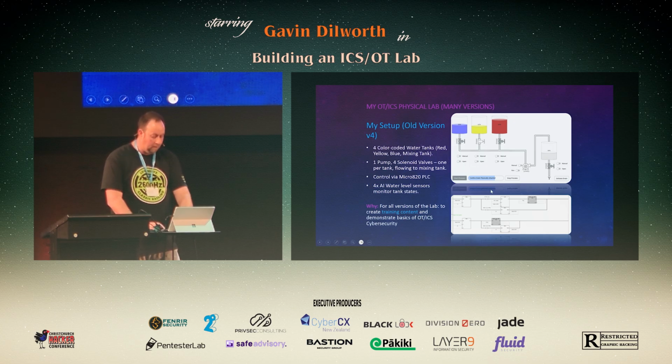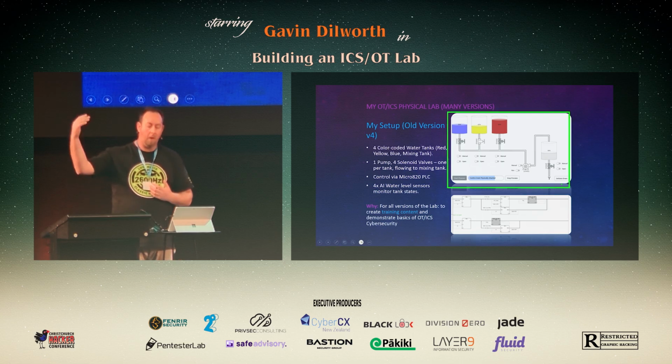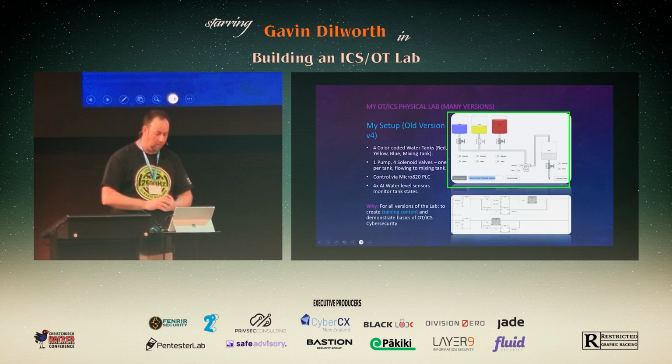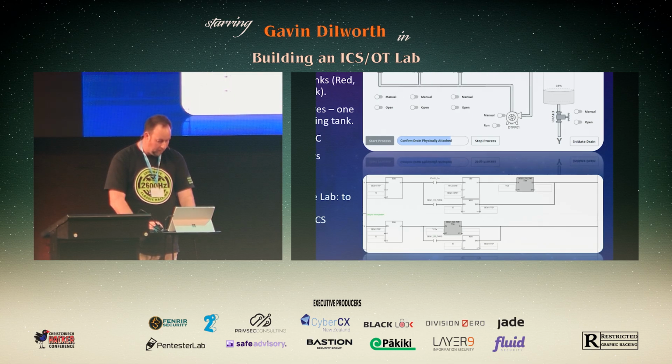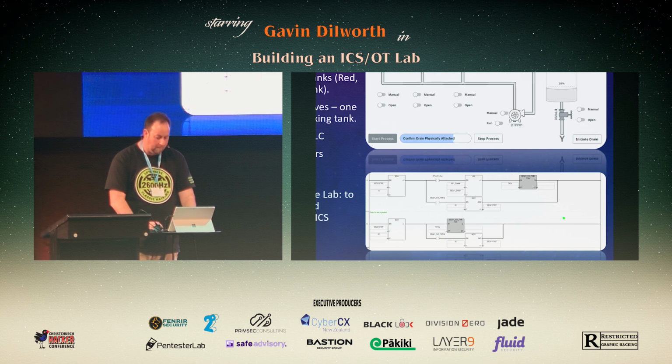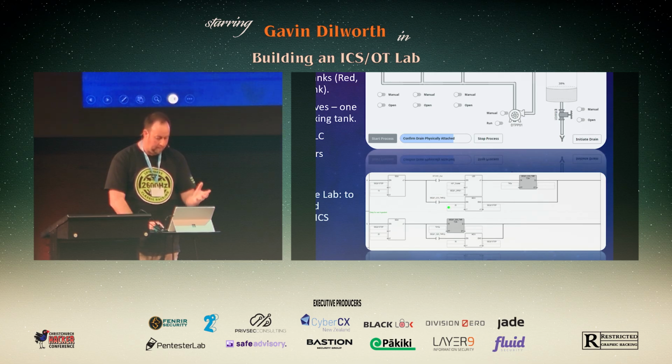So this is the SCADA screen. A SCADA screen is literally just a visualization. Think of it like a web page, just showing you what's going on. And then we've got some ladder logic down the bottom here. Although it doesn't look much like ladder logic, it is indeed ladder. You can see an XIC there, for those that know what that is.